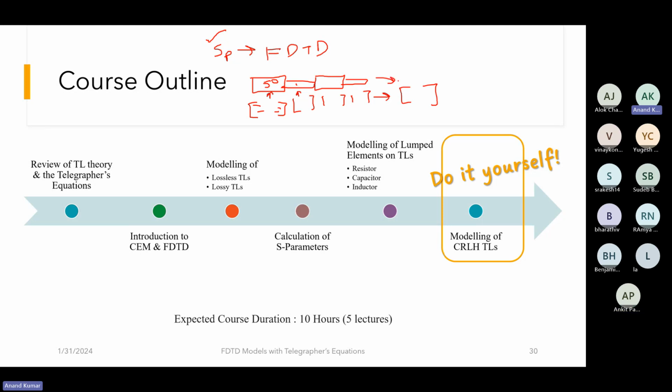There is a formula in Pozar which directly tells you how to calculate the S parameters from the ABCD parameters of the network. So you'll get the S parameters for the entire network. This has to be done by hand, and to ease the calculation, you can write a MATLAB code. You just enter the matrix values, multiply them easily in MATLAB, and convert directly.